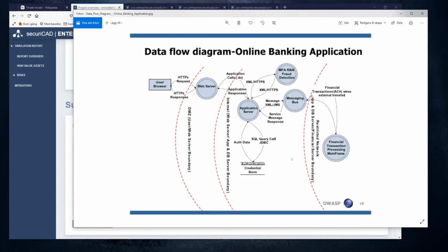And then when it comes to SCADA equipment, that is a similar thing, because if in this restricted zone you have a SCADA control system, an engineering workstation, a historian, etc., and a bunch of network zones forming that SCADA solution, then further down in the architecture you will have things like substations and RTUs that are more limited in their capabilities than traditional servers.